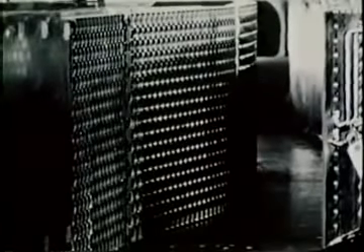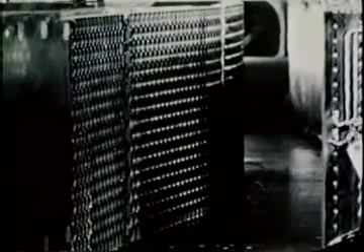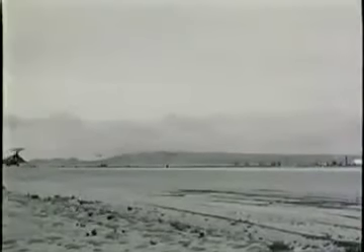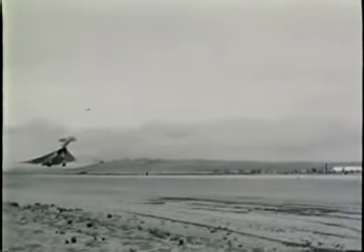Since the supersonic flow is provided by the relative motion, the inlet duct corresponds to our second throat. However, the idea of a fictitious first throat is still useful for understanding the behavior of the airflow.